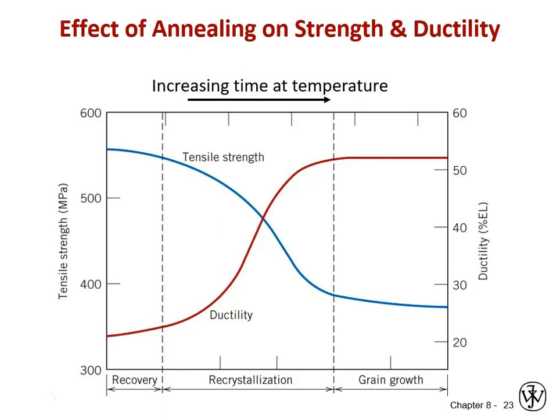And again, if I maybe had a high fracture requirement in service, I could stop halfway through where the lines cross. So at this point, your extent of annealing and the extent of recrystallization that you would want would be dependent on what you're going to do next.